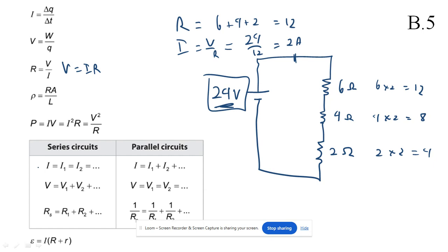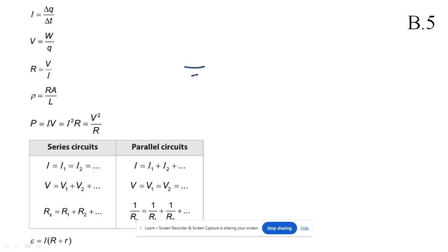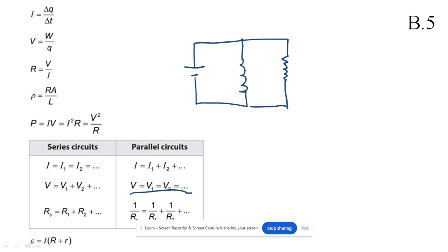So that's what they're saying here. Okay. So remember, a series circuit has one current. It has many voltages. This one's got 12 volts, 8 volts, 4 volts. And then if we look at parallel circuits, a pure parallel circuit is just one voltage, right? It's got one voltage, and that voltage is applied to all the circuit elements. If that's not the case, it's not really a parallel circuit. So this is a true parallel circuit, if I could draw it.